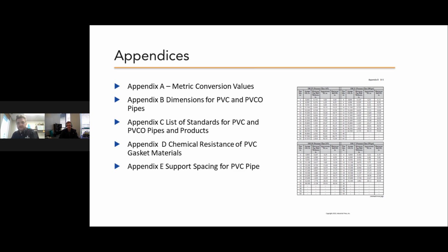Thank you. In your testing, just adding on to this question, I think in your Uni-Bell testing, it had a pipe that had 10 years of exposure and everything passed performance. So the 2-year limit is just a general recommendation. That's not a hard and fast rule. Correct. I believe the pipe that they tested, they left it on a roof in either Texas or Arizona for 10 years and then came down and tested it.